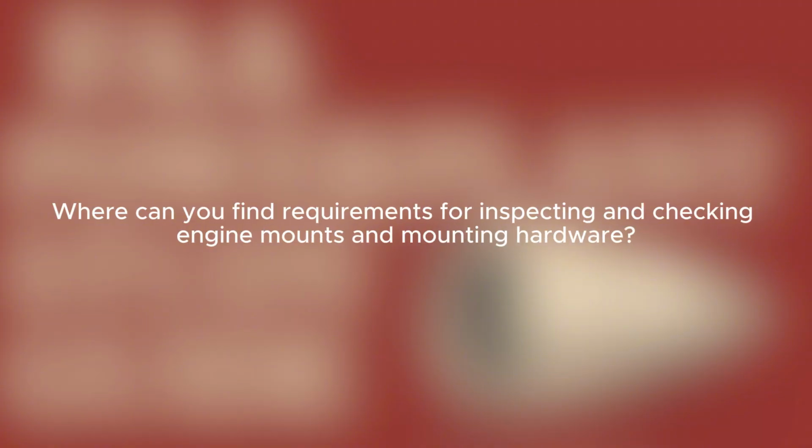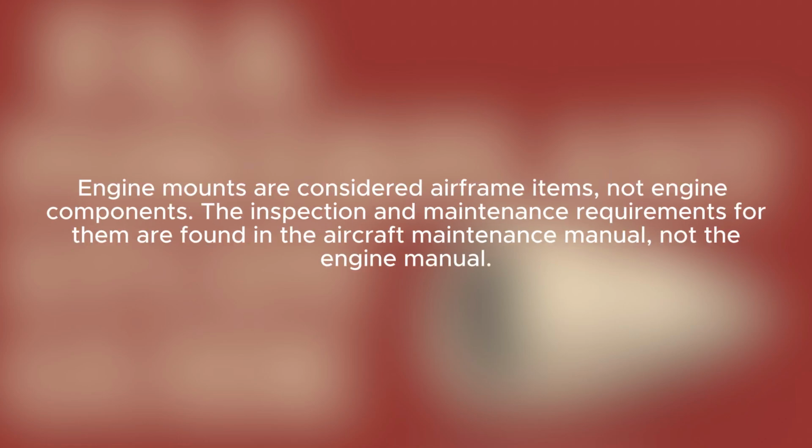Where can you find requirements for inspecting and checking engine mounts and mounting hardware? Engine mounts are considered airframe items, not engine components. The inspection and maintenance requirements for them are found in the aircraft maintenance manual, not the engine manual.